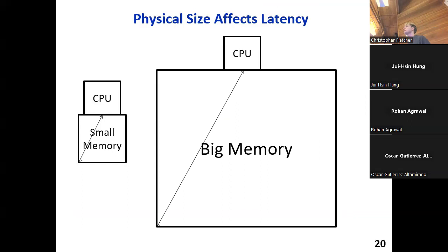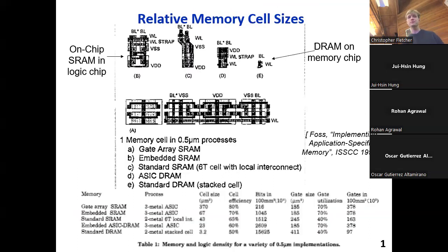DRAM is all about optimizing and maximizing density, at maybe the cost of access latency. It doesn't help you to be dense if you're small. So people typically design DRAMs to store lots of bits, meaning that they're larger. The speed of light is constant, so the time it takes to get bits out of this very large DRAM array is commensurately slower. Signals have to travel farther, they have to potentially fan out to more locations, and so on.